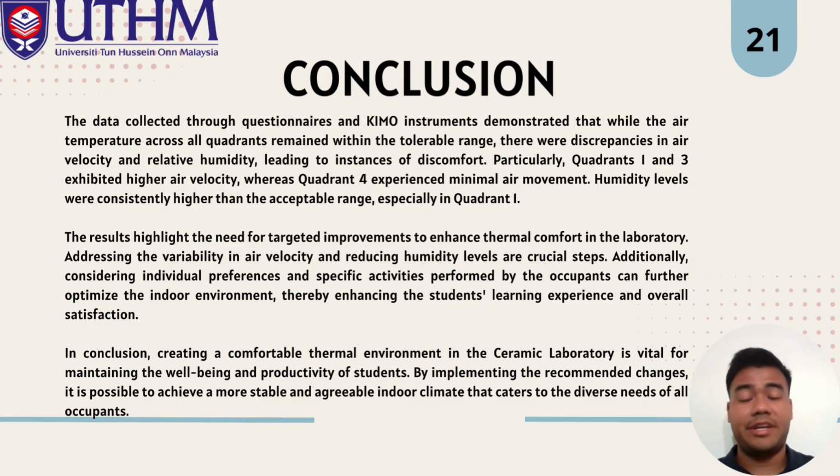For the conclusion, the data collected through the questionnaire and Kimo instrument demonstrate that while the air temperature in all quadrants remains within the tolerable range, there were discrepancies in the air velocity and relative humidity, leading to instances of discomfort. Particularly, quadrant 1 and quadrant 3 exhibit higher air velocity, whereas quadrant 4 experienced minimal air movement. The humidity levels were consistently higher than the accepted range, especially in quadrant 1. So the results highlighted the need for targeted improvement to enhance thermal comfort in the laboratory.